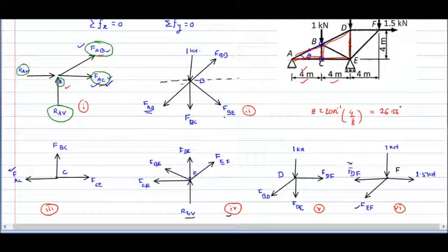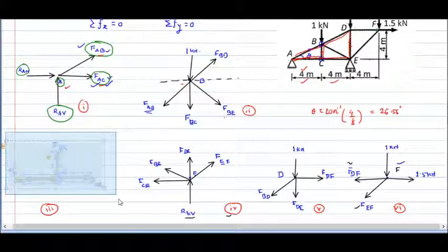So we can choose either C, or once again point F, where there are also two unknowns, as we saw in the earlier step. Any of these points we can choose. So we will select this point C. There are no such restrictions. If the same number of unknowns are there, then we can go with any joint. It's an open choice. So I am going to consider this point C and apply the conditions of equilibrium as we applied for the second figure.